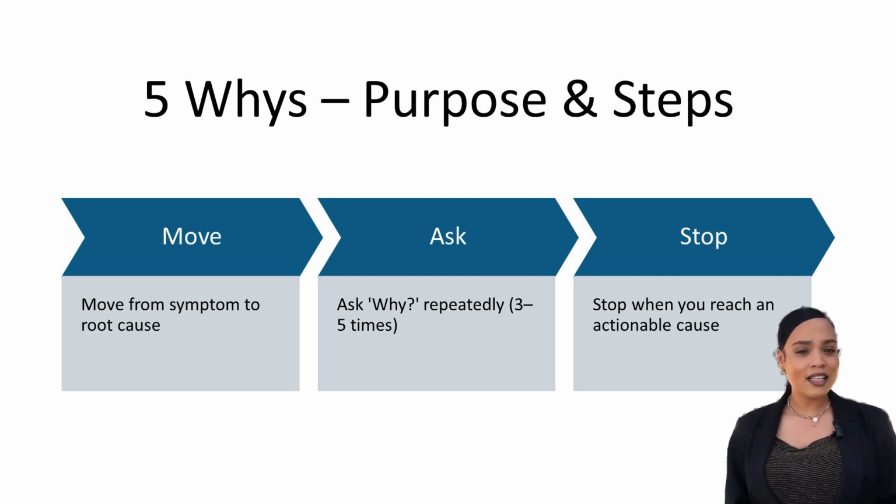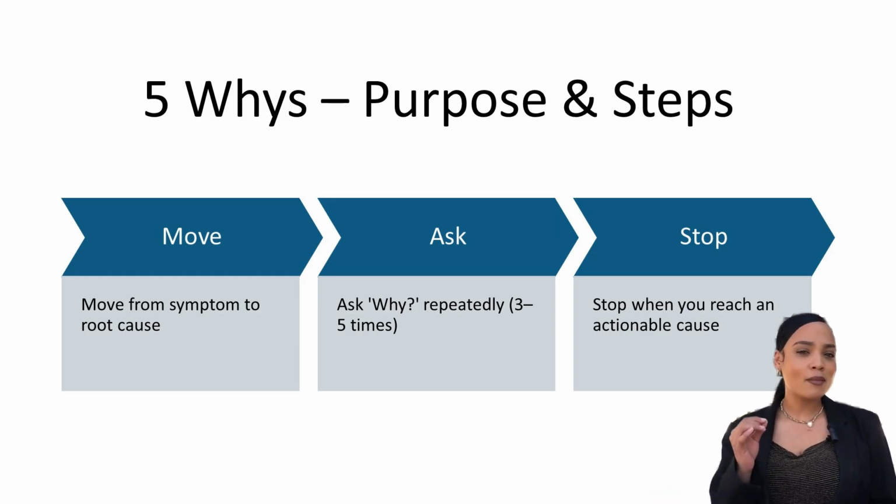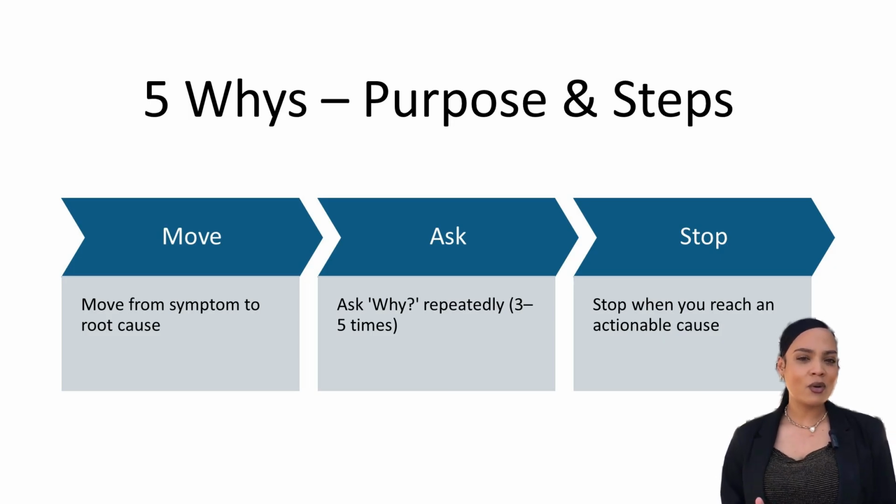Step 3. Take that answer and ask, why did that happen? Why did the motor overheat? Because the cooling fan was not working. Step 4. Continue to ask why until you get to a root cause that you can act on. You might end up at, because there was no preventive maintenance schedule for cleaning the cooling system. We usually reach a root cause between the 3rd and 5th why.